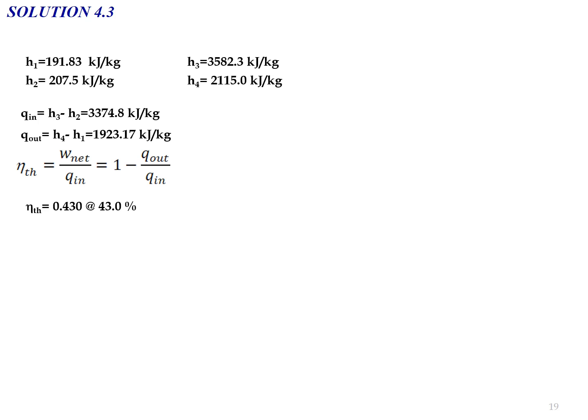If you compare the values of thermal efficiency between A, B and C, question C or case number 3 has the highest value of thermal efficiency, where for question C we use the third method, where we fix the value of T3 and then we increase the boiler pressure. Okay.